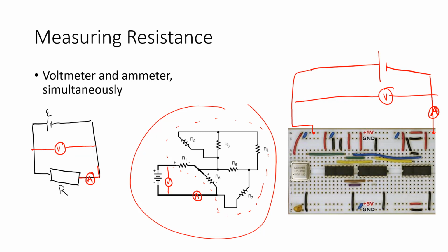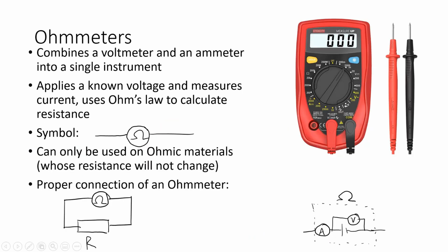Now keep in mind this is always going to work, but for example, for this circuit, the resistance will change at different currents when different things are going on. So you do need that voltmeter and ammeter. You can only measure the resistance in a particular state. That resistance can possibly change, especially since it's not a pure resistor circuit. So even though in general resistance can change, we know that for resistors, they're ohmic, so the resistance is constant.